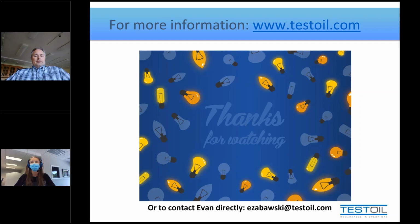In the test oil analysis report, does it recommend saying you should replace the oil? Well, we may from time to time, within a comment, suggest that as one of two options, but we are not the final deciders of that particular action. The reason a lab will never say you must change your oil, absolutely without fail, is we don't understand what it takes to do that. When you send us a sample, we don't know necessarily that it's a 5,000 gallon system, that you're going to need 2 rail cars worth of oil, that you're going to have to shut down, go offline, suffer regulatory fines. We don't know this.